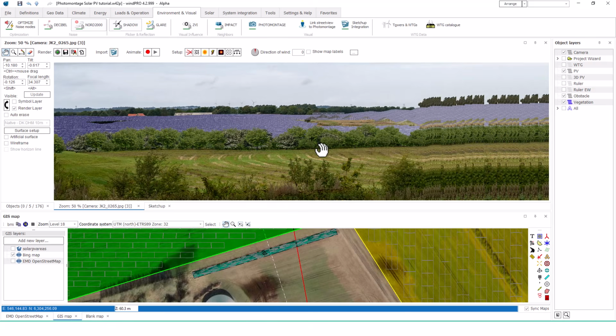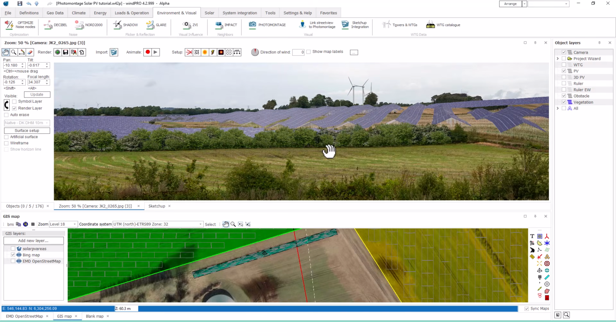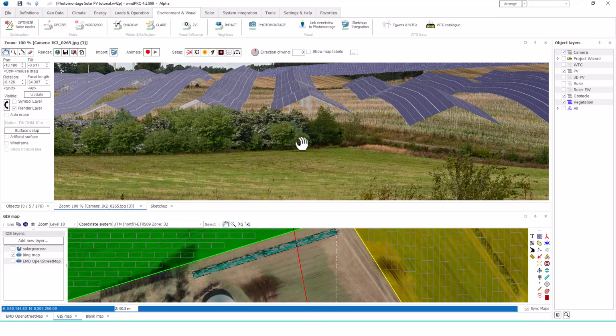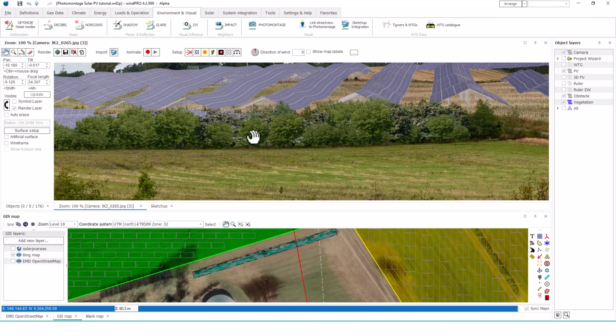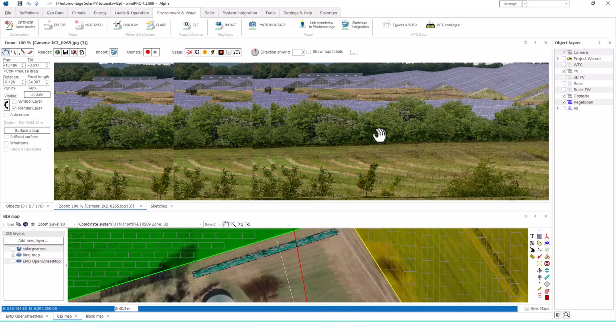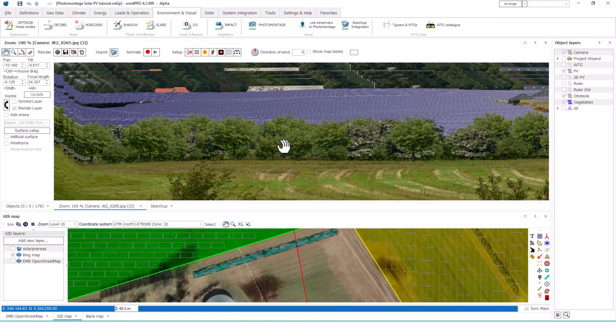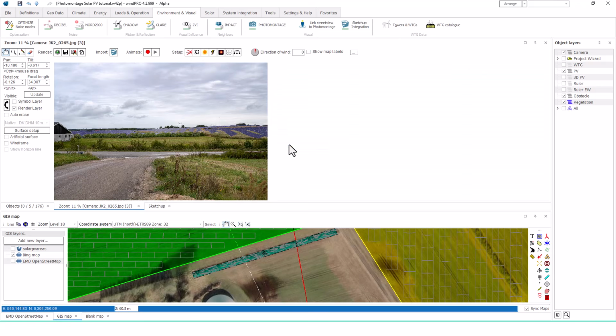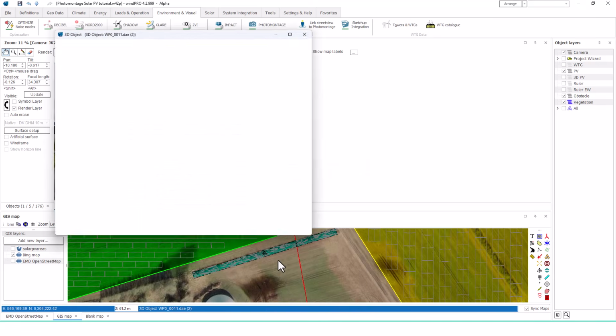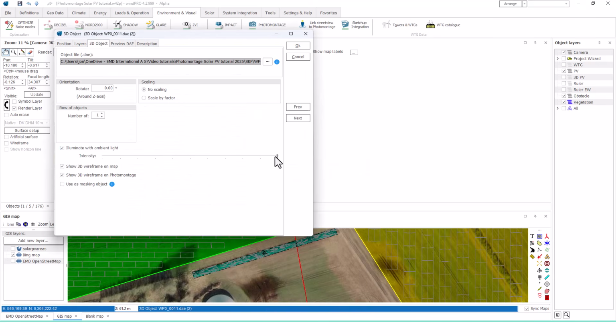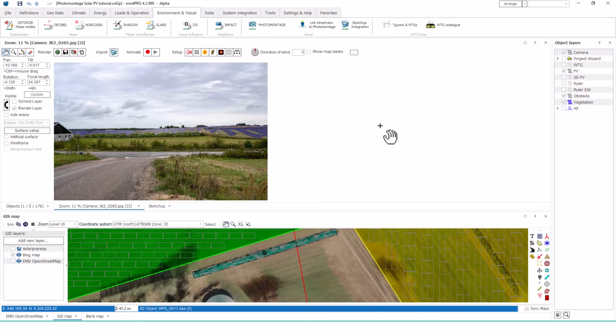If you think it is not dense enough or want to add some additional trees here and there, then you could either move or copy some trees in SketchUp before exporting to windPRO, or you could just run the vegetation creator multiple times. If you find it is too dark, you can change the light settings on the 3D object. You can also do it in post-processing in Photoshop, as I will show later.